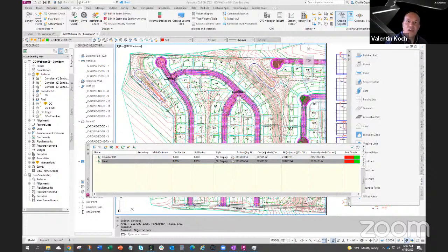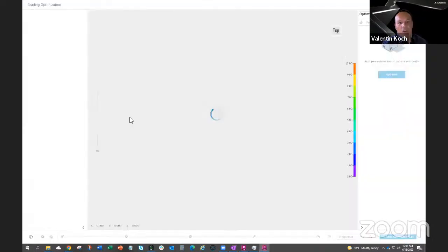But basically, with a bounded point, you can put a lower bound. So you have your EG. You would say you can't go lower than, what was it, 1 foot? Yeah, you would set the bounded point's lower bound to 1 foot below your EG, and that would prevent it from going deeper. So in your landfill project, you would probably put as many bounded points as you can. It's maybe a little tedious, but I would probably do that.